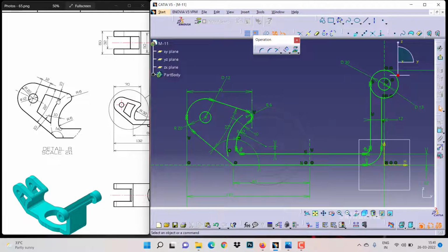So once it is done, we have to connect this with the lines. So let us close it. So connecting one line over here, fine. Then one more line over here, it need to come perpendicular to each other. Then I'll close it like this. So in this, you have to delete these tangency, delete it off, and make these two lines parallel to each other.